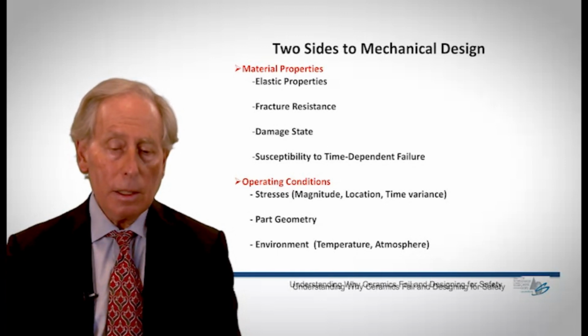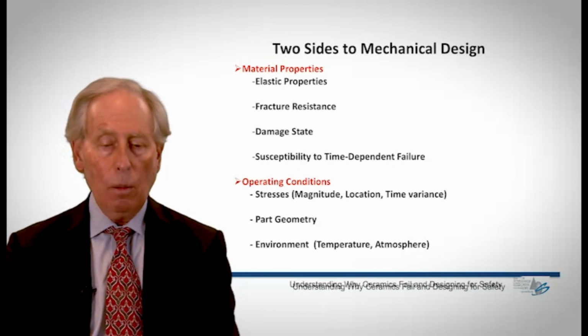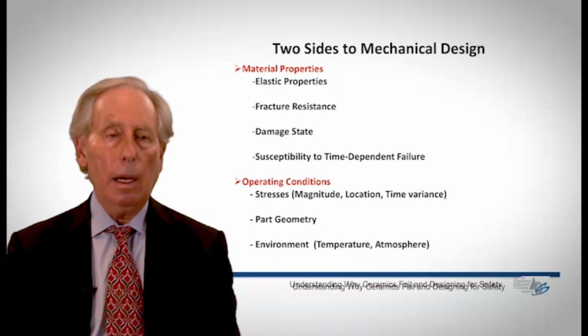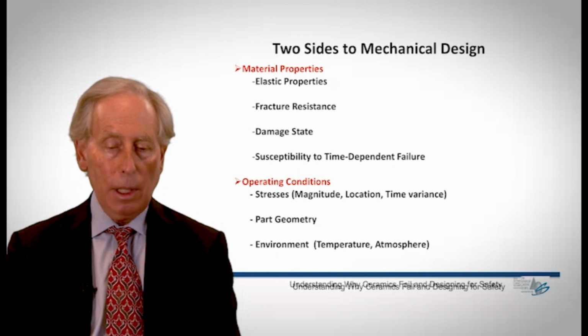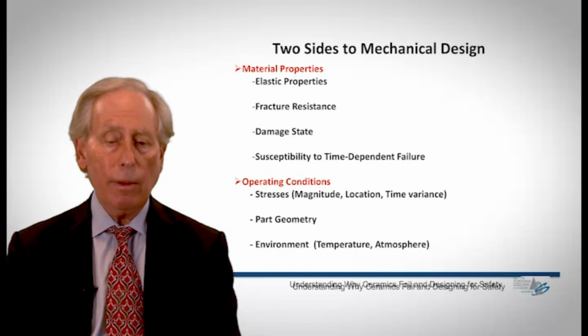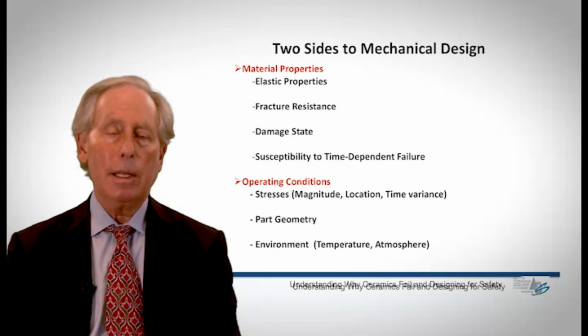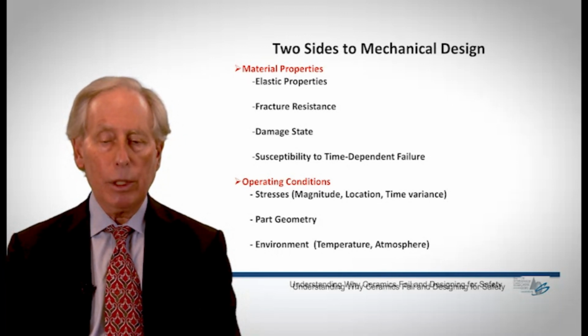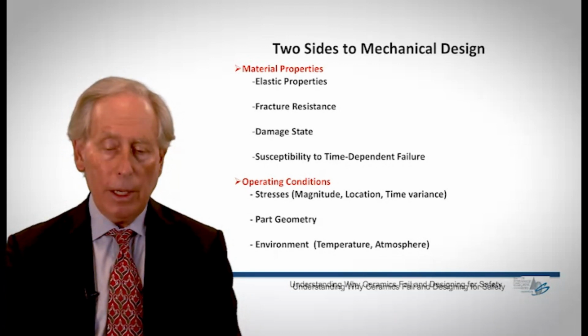And the other side is obviously the operating conditions. What are the stresses, the magnitude, the location, the time variability? If I'm looking at windows, how hard does the wind blow, over what period of time? These are all important variables. What's the geometry of the part? What's the environment? Is it operating at low temperature? Is it operating in a moist environment? These are all important things that I need to think about as I go about choosing materials for any particular application. But there are other issues as well.